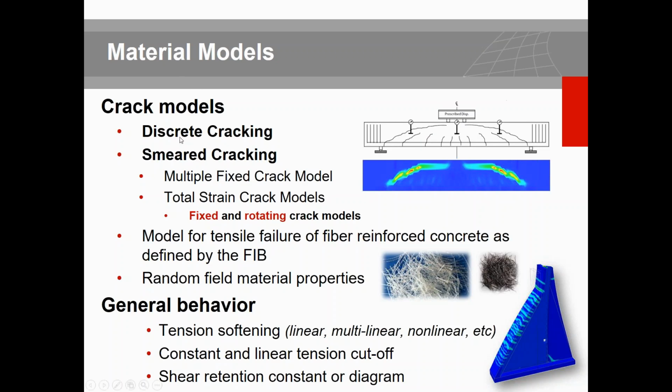I briefly touch base on some of the known ones, but the rest are available. We can discuss if it's needed. For the crack model, you can use the discrete crack model if the crack is already apparent and you want to see how this crack is pinching, like opening and closing subjected to the loading. So in that case, you may use the discrete cracking approach.